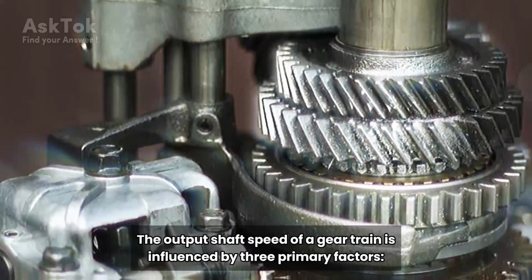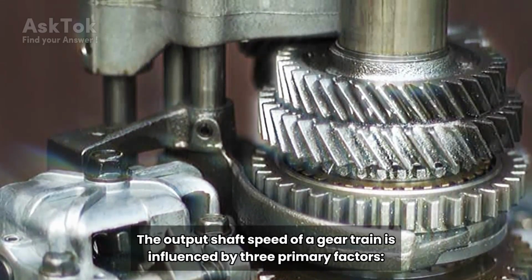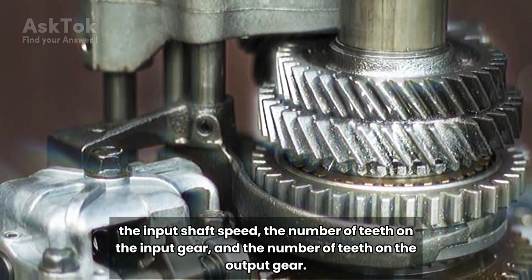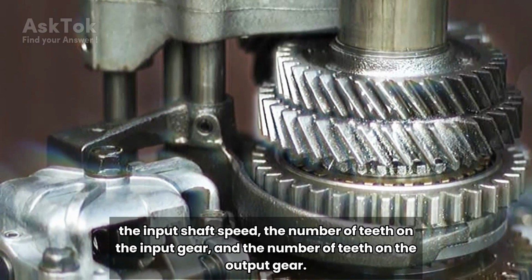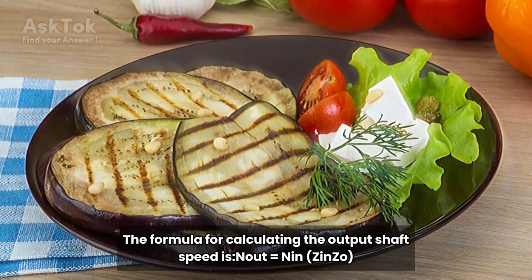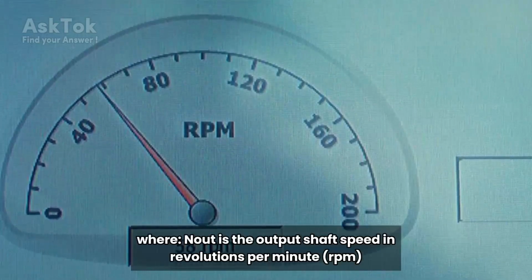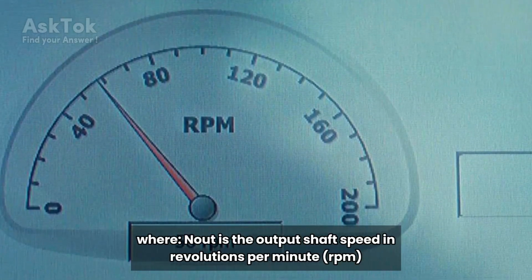The output shaft speed of a gear train is influenced by three primary factors: the input shaft speed, the number of teeth on the input gear, and the number of teeth on the output gear. The formula for calculating the output shaft speed is Nout equals Nin × Zin/Zout, where Nout is the output shaft speed in revolutions per minute, RPM.